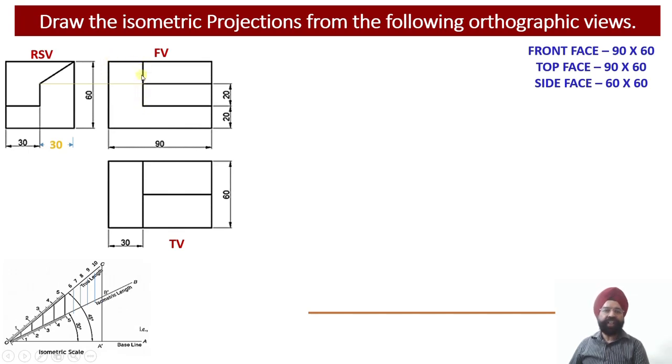Now once I have got this vertical component which will be the flatter component, now I need to look into the second element. My second element, you can check, this is my flat face. So this flat face corresponds to this rectangle. Please check this out. This corresponds to this second segment where I am able to view the true shape of this flat segment in the front view. So the true shape of this flat segment is visible to me in the front view. Whereas my third element is the slanting shape over there. This is a slanting surface.